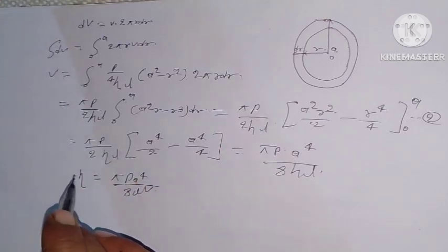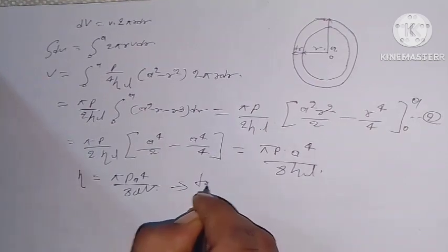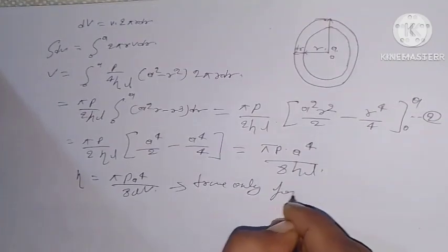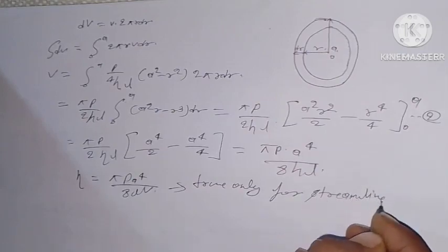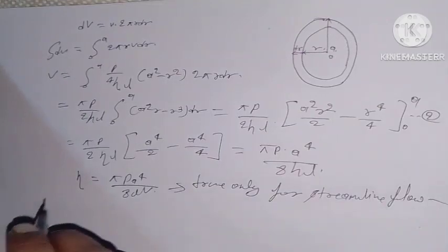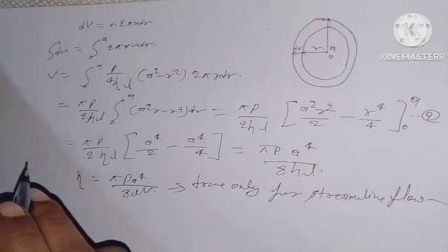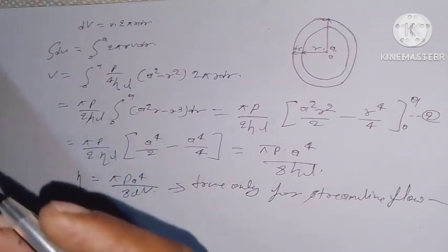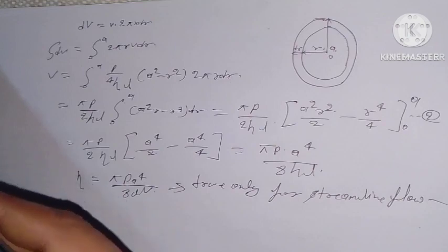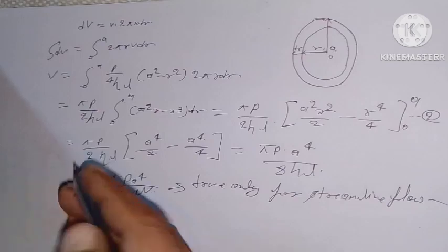This is Poiseuille's formula for the flow of liquid through a capillary tube. It is true only for streamline flow. The flow is streamline, as we know, when the average velocity of flow is less than the critical velocity, but the critical velocity is inversely proportional to the radius of the tube. Hence the above formula fails in the case of a tube of wide bore. Moreover, the pressure difference between the ends of the tube should be small in order to have a